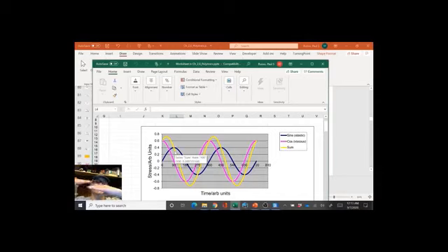That happens in the middle somewhere. Okay? So the elastic term and the viscous term are 90 degrees out of phase. And when you take things that are out of phase and add them, the sum is also out of phase. Okay? It acquires a phase sort of in between.